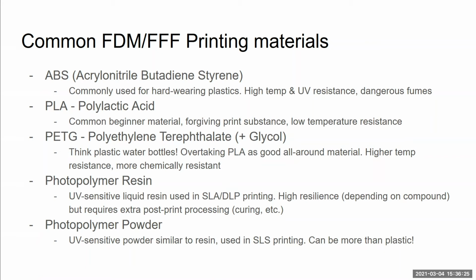And one of the big things that PETG really succeeded at is that it is less temperature sensitive once printed, so it doesn't deform as much as PLA. It's really popular because PETG took on a life of its own at the beginning of the COVID-19 pandemic, because that's what people discovered was the plastic that was good enough to 3D print the masks and the face shields with. They could stand up to the hospital sanitization program. So PETG sort of had its day in the sun at the beginning of the pandemic last year.